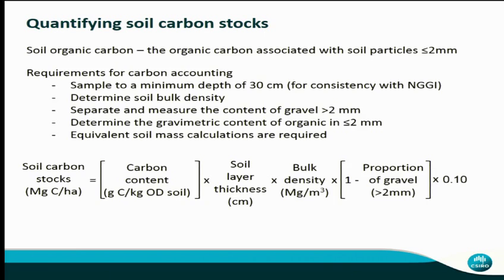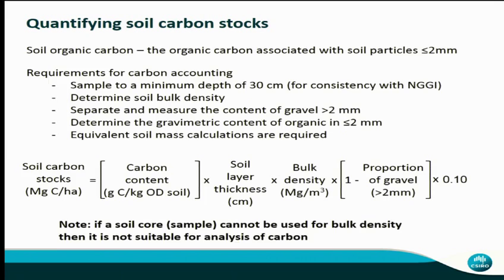One thing, and I'm guilty of this when we started the soil carbon program, the bulk density question always comes up. Measuring bulk density, we've got to be so careful about getting that exactly right. And I would now say, after running through the carbon program and the work we've done, if a sample's not good enough for bulk density, it is not good enough for carbon. And this idea that you can take a grab sample for carbon, then go get a bulk density number, or be very careful about your bulk density sample, is not correct.